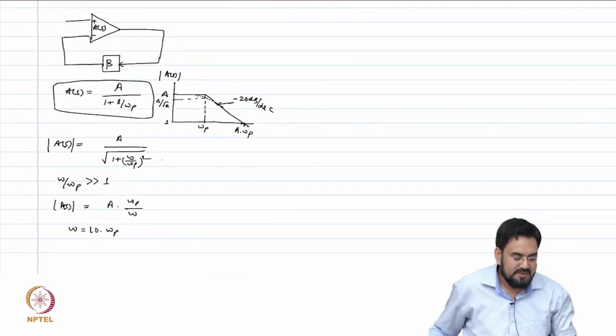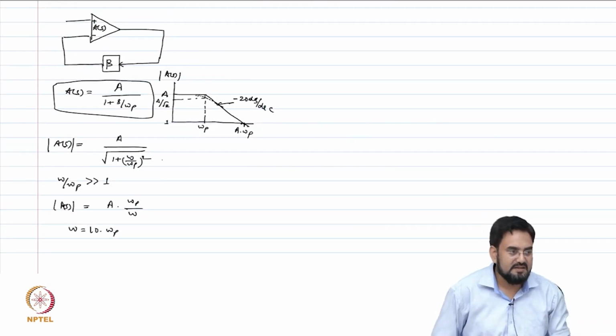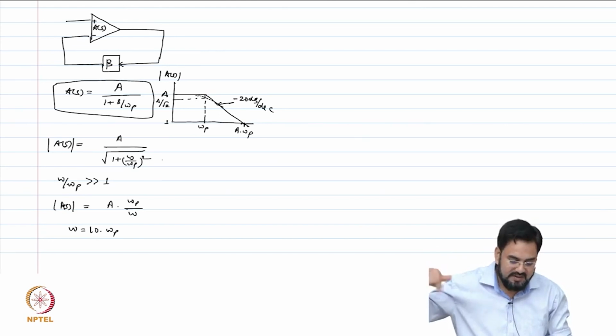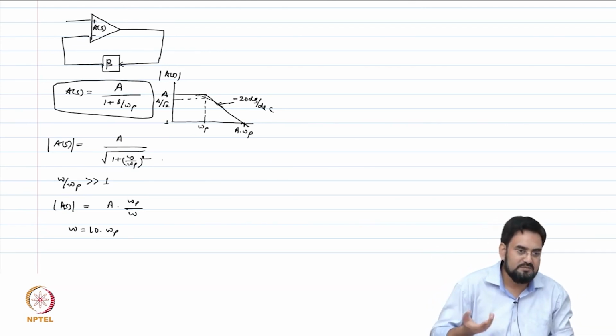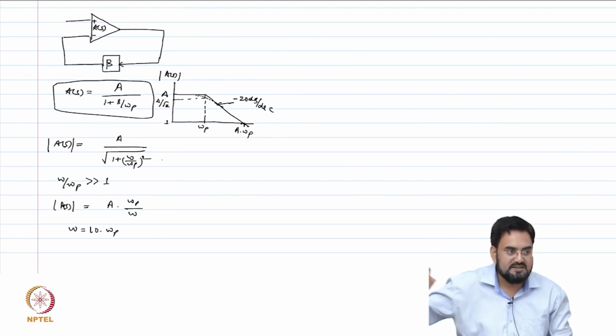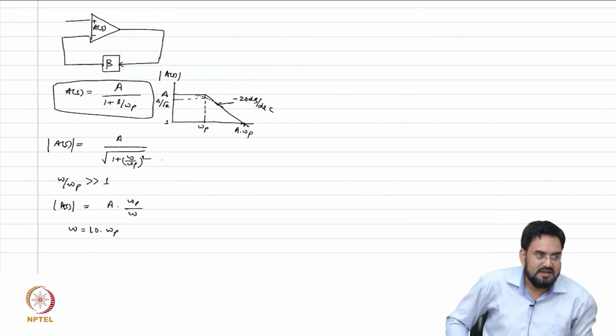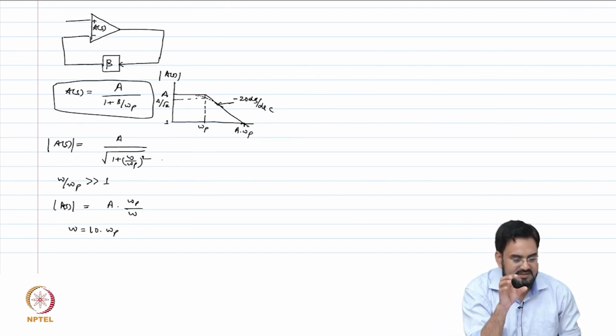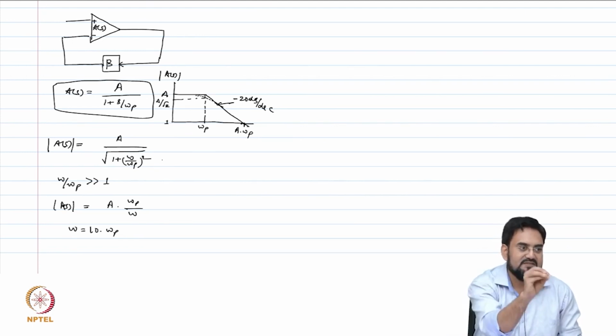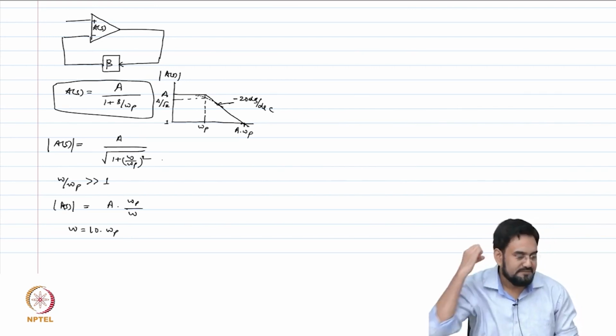But there is a relationship between, when you define in the closed loop for the second order system, you remember damping factor zeta and all those. So there is a relationship between zeta and your phase margin. I will talk about that later. And by looking at the phase margin, you can intuitively say that your zeta factor is somewhere around that.